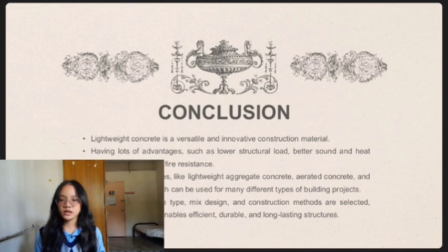In conclusion, lightweight concrete is a versatile and innovative construction material. It offers many advantages, including reduced structural load, improved sound and thermal insulation, and higher fire resistance. Lightweight concrete is available in various forms, such as lightweight aggregate concrete, aerated concrete, and no-fine concrete, making it suitable for a wide range of construction projects. When the correct type, mix design, and construction methods are selected, lightweight concrete can produce efficient, durable, and long-lasting structures.